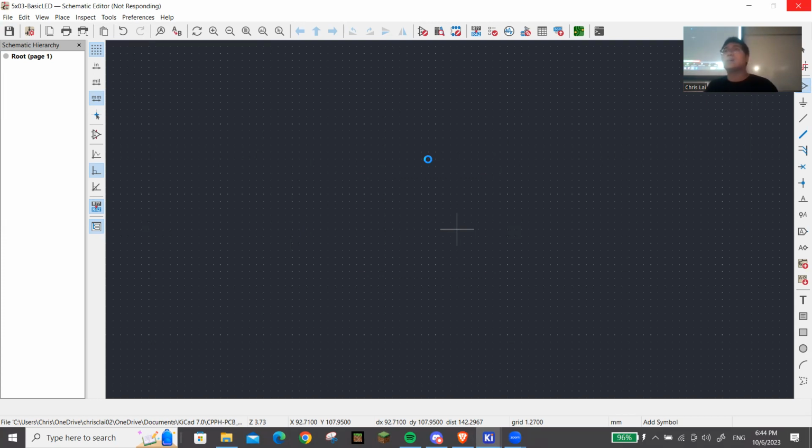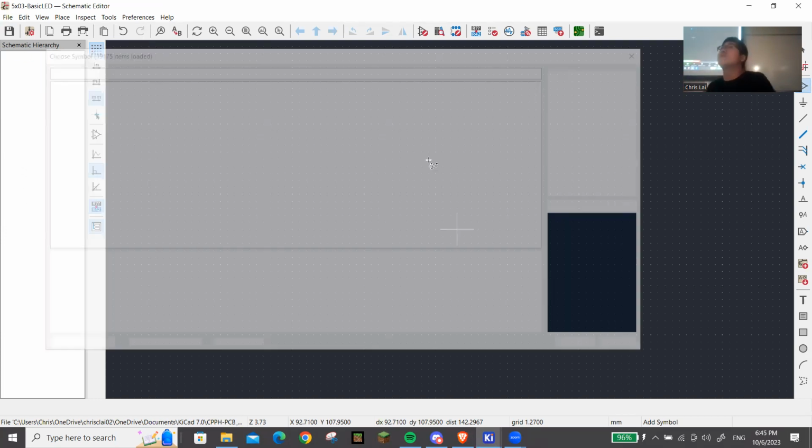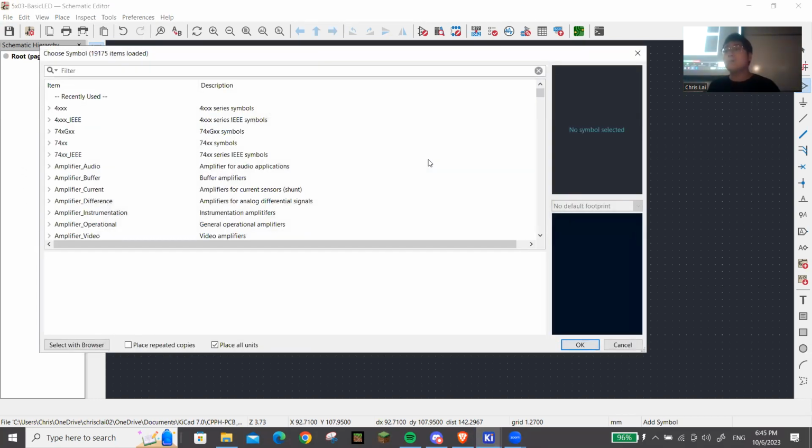And you can find these on online ECAD repositories, or you can ask a librarian, if you're working on this for a company, to make a symbol for you. I've had to make my own symbols before, like on some of these boards. If you see these switches here, these switches aren't actually on KiCAD. These are not even supposed to be on a PCB. So I had to make this symbol and footprint by hand. And there's a whole art to doing that I'm not going to explain today. But for this workshop, we're only going to use the most common symbols.